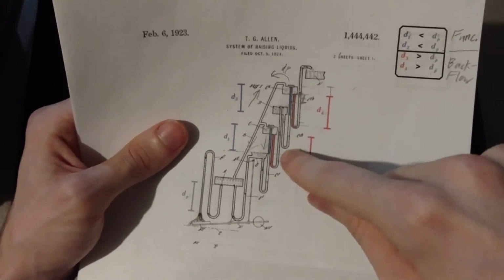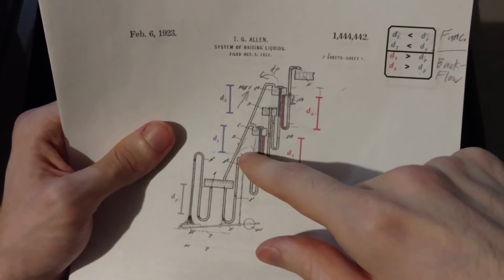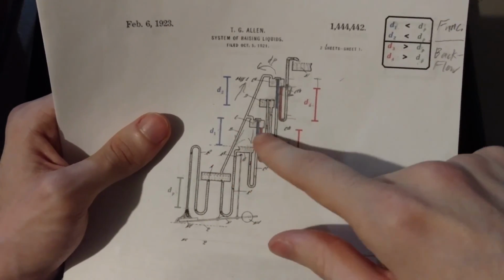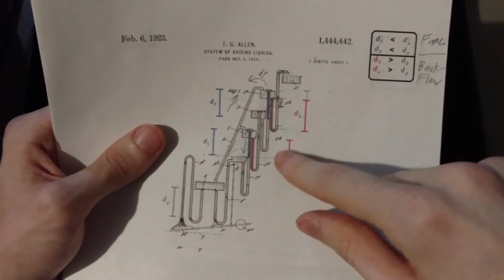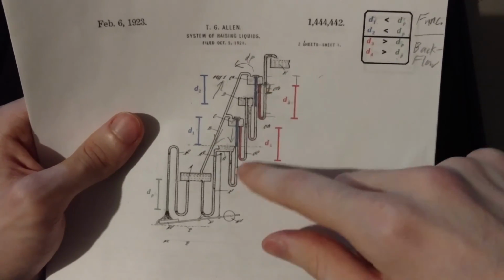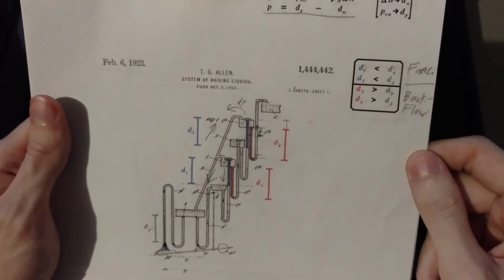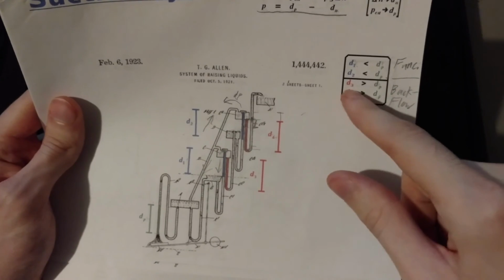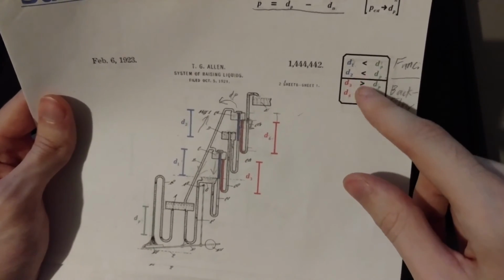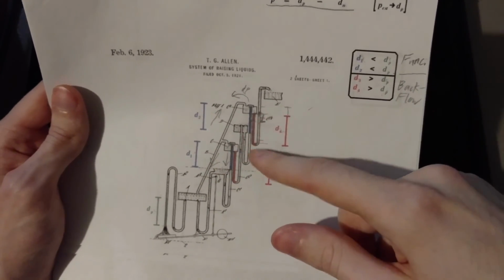But because of the proportionality of those traps in relation to the distances between the feed tank, the operating tank, and the end of that siphon, because everything here is in the right set of proportions, you actually don't need check valves, which is really cool. So as long as you keep these inequalities, all these proportions, as long as this is done properly, you won't have to use any check valves in your setup.